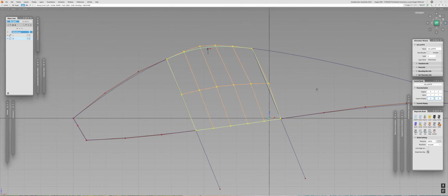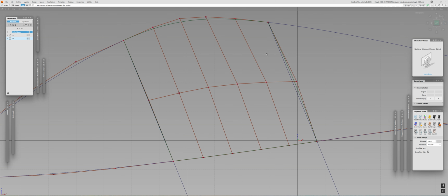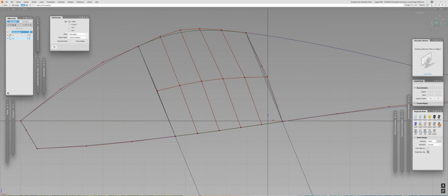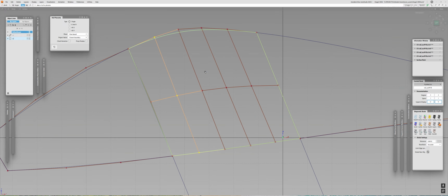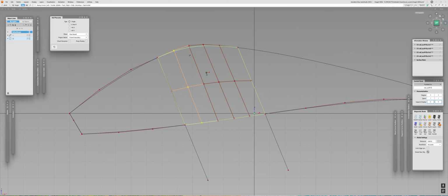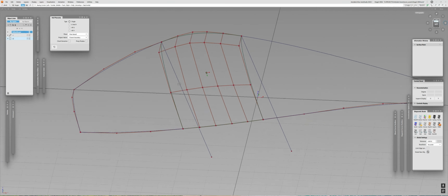Now let's try to fix the bend a little bit. So I will use the planarize hole command, and I will just planarize the holes. Now there is an option for all U and V, or only U or only V. I just prefer to do it manually myself, one by one.